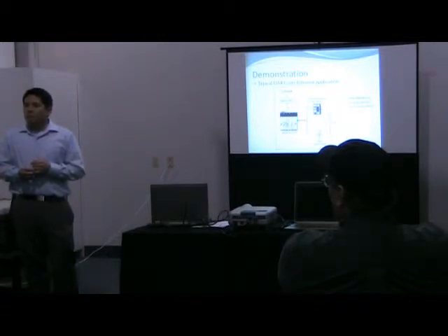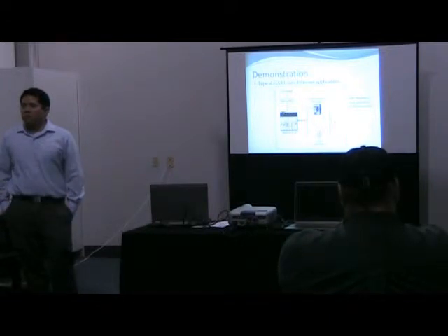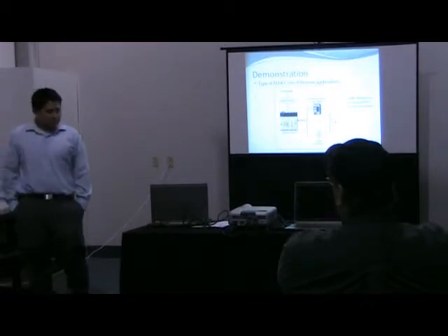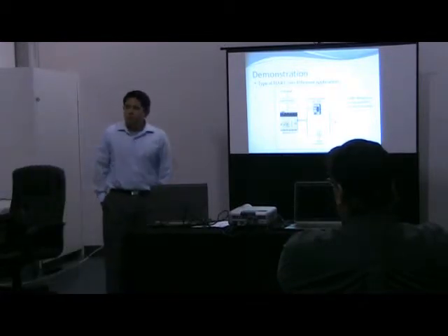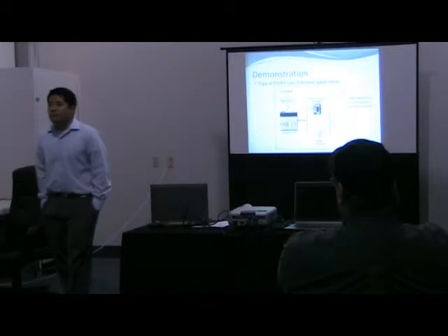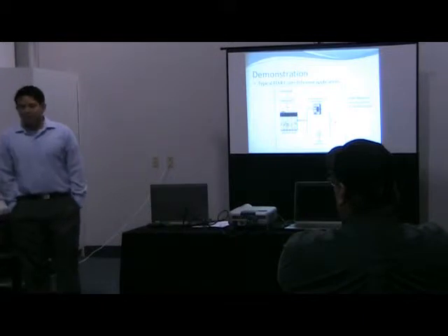So you have to be careful about that. You might end up with an isolator at some point, but it strictly depends on how that card is configured, whether it's designed for a current loop or for a voltage source. If it's a voltage input with a 250 ohm resistor on it, then loop integrity is not usually impacted. But if it's a current source, then you have to be careful about how that interferes with your AI card on your Modicon. So there are concerns. You can't just put it out there; you have to make sure your loop integrity is maintained.